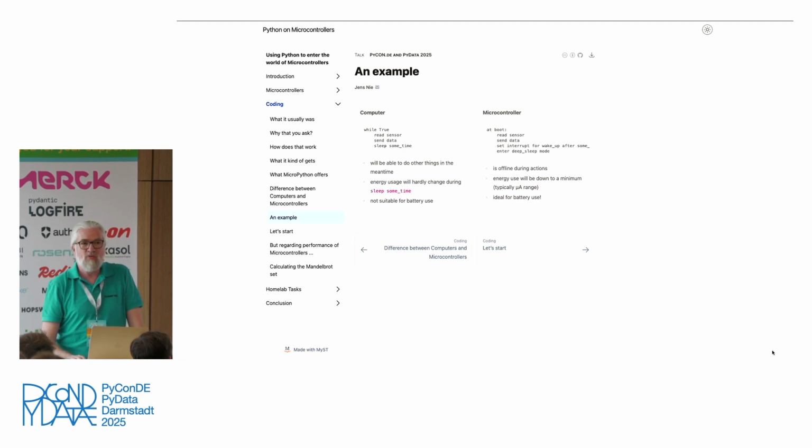And that is ideal for battery usage, because these deep sleep modes in microcontrollers allow you to get down to microampere level of usage. And then with a single battery, that thing can run for months.